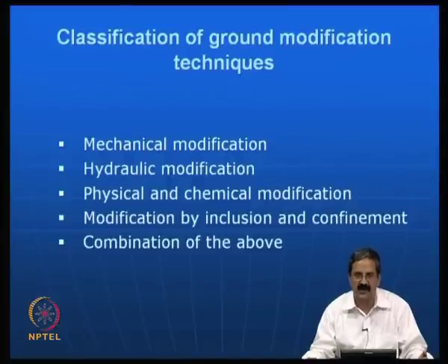Similarly, in the case of soils also, we put the reinforcement, whether in the form of geogrids, steel grids or geomembranes. There are so many materials one can put in the form of reinforcement in soil, which we call reinforced earth or reinforced soil. The advantage is that whatever load is on the soil is now taken care of by the friction between the soil and reinforcement.